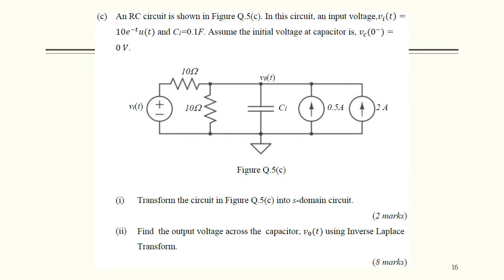The last part of the Laplace transform usually would be the application of Laplace transform in circuit analysis. As usual, you need to start with converting the given circuit into an S-domain circuit. Transform all components into S-domain functions and then solve the circuit by using your knowledge from circuit theory. Lastly, use inverse Laplace transform to get your equation in T domain.